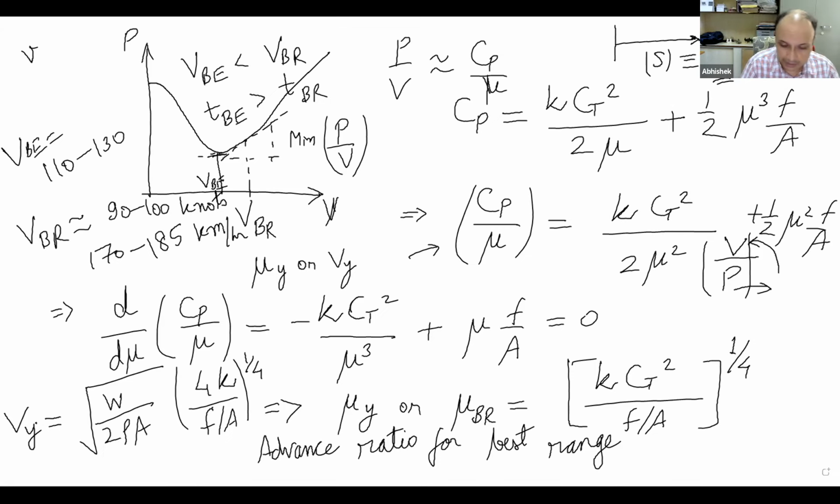Because here I want to see what is my power consumption per unit of distance traveled, not per unit of time. So instantaneously, best endurance may consume less power, but overall it will consume more power because of the extra time taken. Yes. Because the main concern is to get maximum distance, not maximum time. And distance is a function of velocity. Therefore, that comes into the whole mix of things.